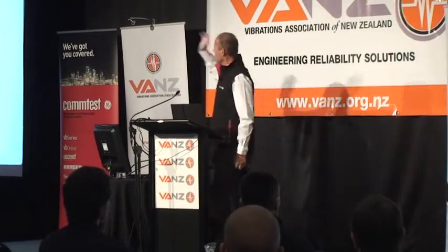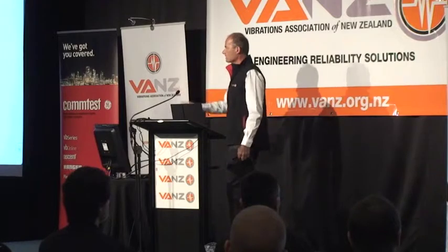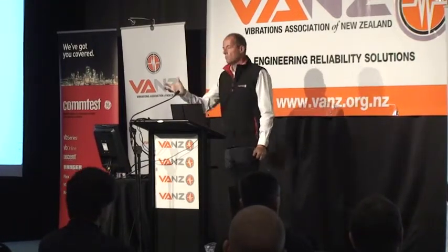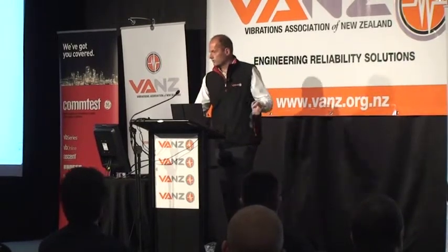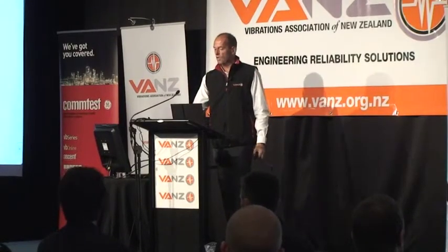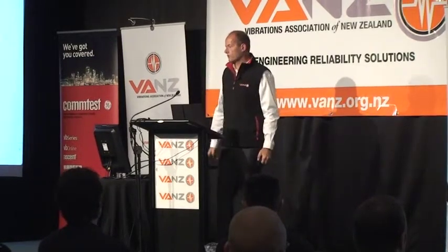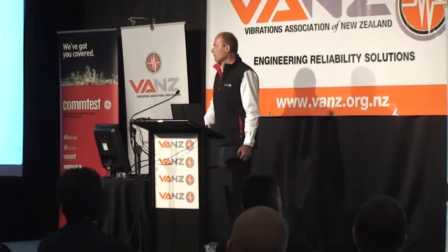Kidding, of course. But from an acceptance testing point of view, we use condition monitoring skills. When the alignment job's done, when the bearings are installed, when the machine's being commissioned, the condition monitoring guys check the machine and make sure it's all good. And then, of course, we keep monitoring the machine. We keep making sure it's clean and adjusted and all those things to make sure that it will remain reliable.